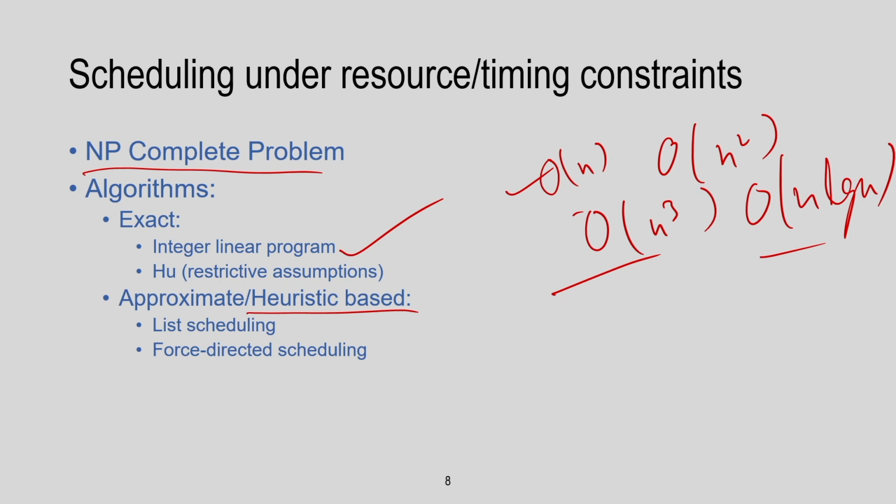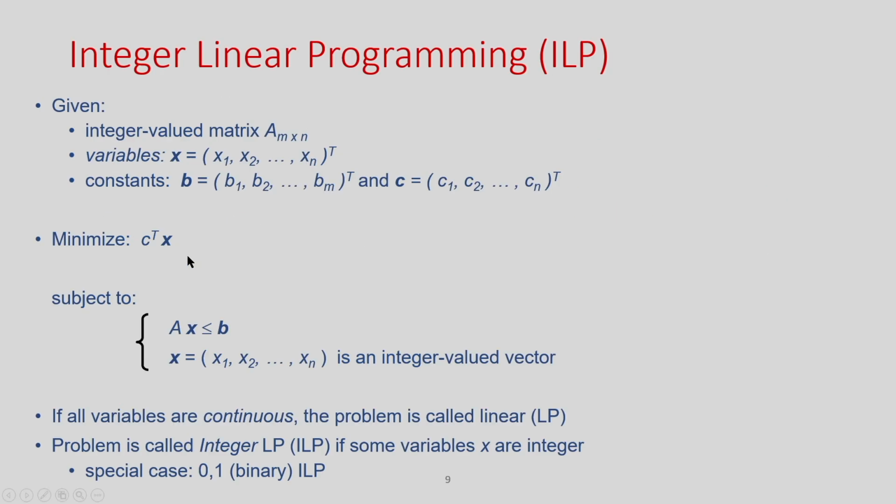Okay. And since the running time of these EDA tools is of prime importance, most of the time we usually go for this heuristic based solution to solve the scheduling problem. So, we are going to discuss all such problems in this particular course. Today we try to see how we can model this scheduling problem using ILP, okay, integer linear programming.